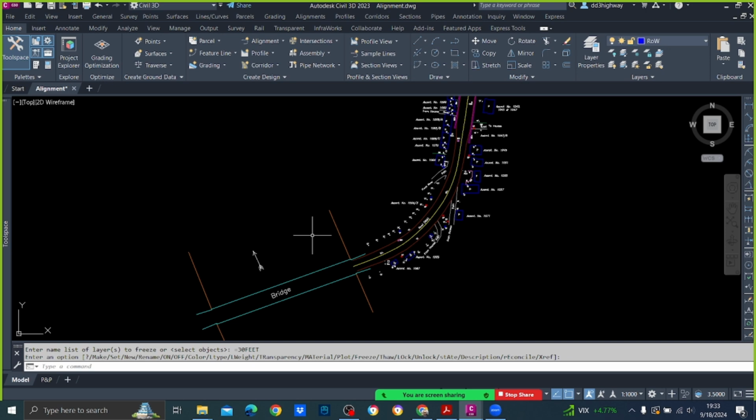Computer design. But when it comes to road planning, there are desk study, then the reconnaissance survey, and then preliminary survey, detailed survey. All these things are for a new road. But when it comes to a rehabilitation road project, you don't do all these things. But one thing you have to do is consider what is the design speed that you have to follow. Now, usually in Sri Lanka, there are two design speeds. One is 50 kmph, the other one is 70 kmph.